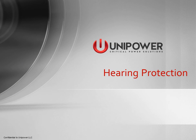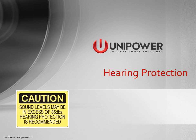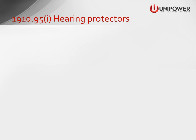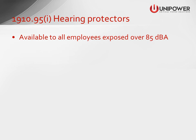Hearing protection. UNIPOWER recommends that hearing protection be used for any sound levels that exceed 85 decibels. There is a number of hearing protection devices that can be used to protect your hearing. Hearing protection must be made available to all employees exposed to any noise level higher than 85 decibels.